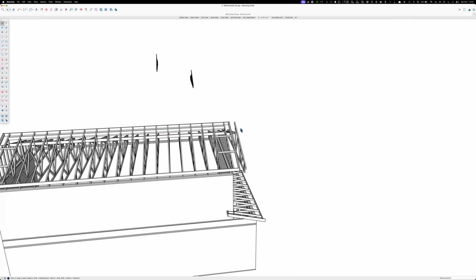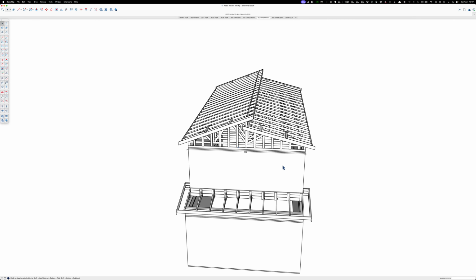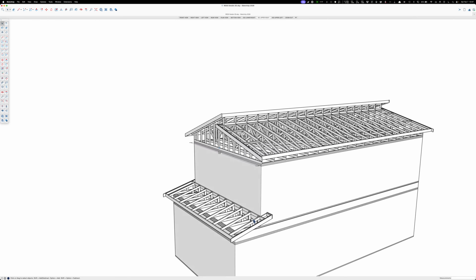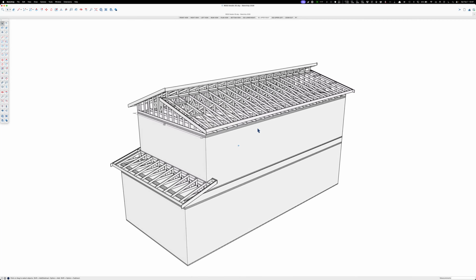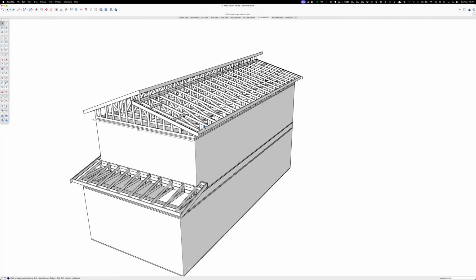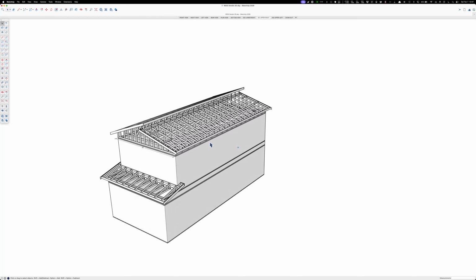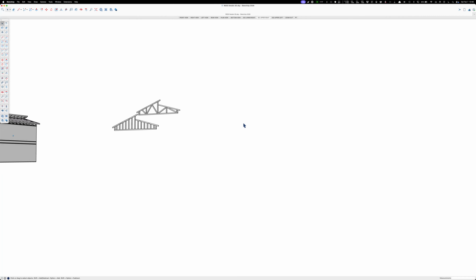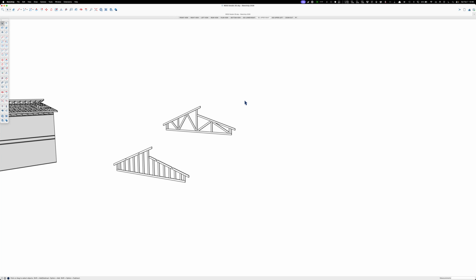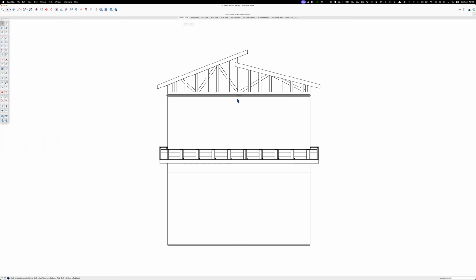That's how that works. So this is kind of a speed course in doing CAD. SketchUp is a little slower because you design each piece. And if you're really smart, you tag everything so that you can turn different layers on and off. I didn't even do the wall studs or the wall framing. A lot of times I'll do that, but on this one I just needed to show the roof. And then front view is a scene, takes me to here.